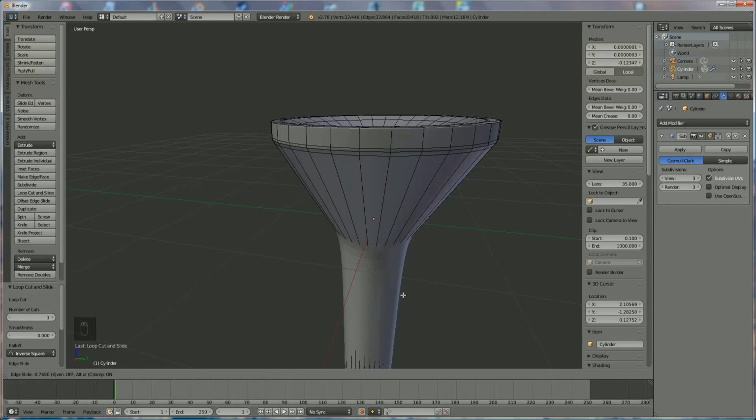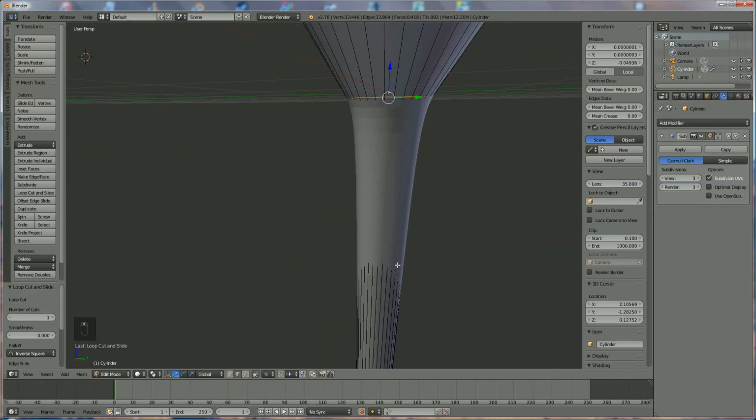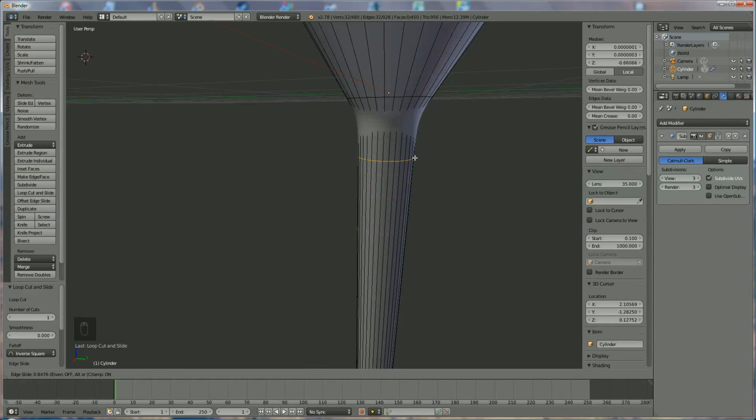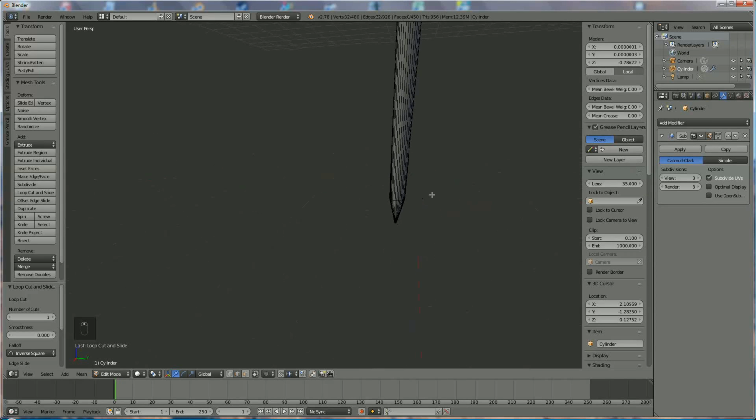So if you go directly to what we already designed, then you have a very small circle. If you want a larger circle, you bring it up a little bit. That's the first point. Now underneath you can do the same, so you can press Ctrl R again, click on that one and bring that one up, and I think this is looking okay, so this is a nice circle, and underneath we have the same over here.